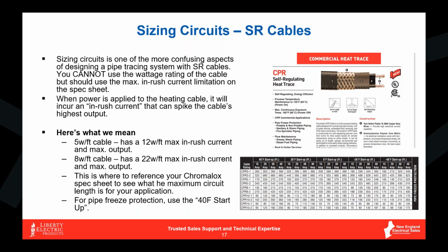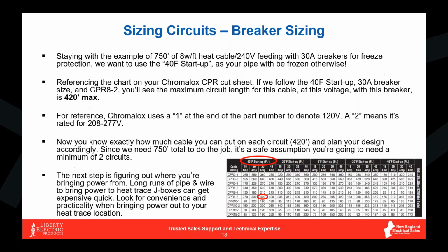So, really, if we stayed along one of these examples, in this particular case, I basically played a game here with a 750 foot length of 8 watt a foot cable, at 240 volt with 30 amp breakers for freeze protection. So again, you're going to reference exactly what I've got circled here, as far as, okay, I know that I can use this for a freeze protection application.